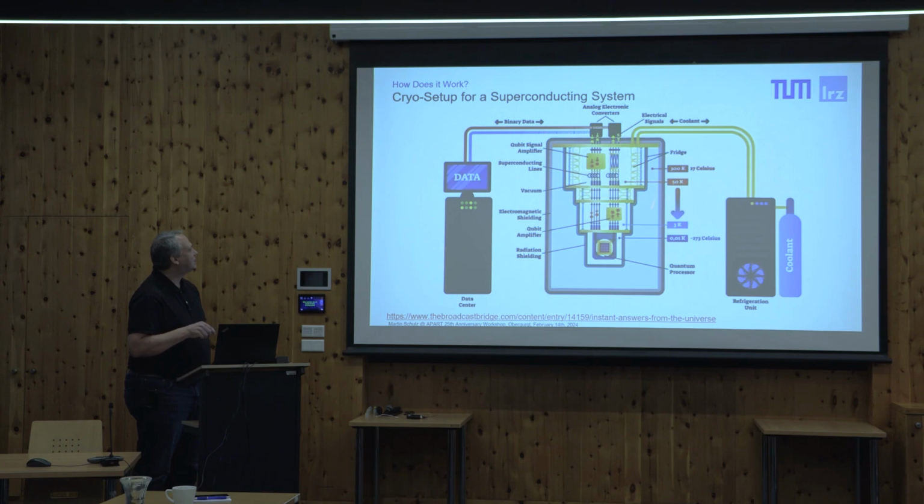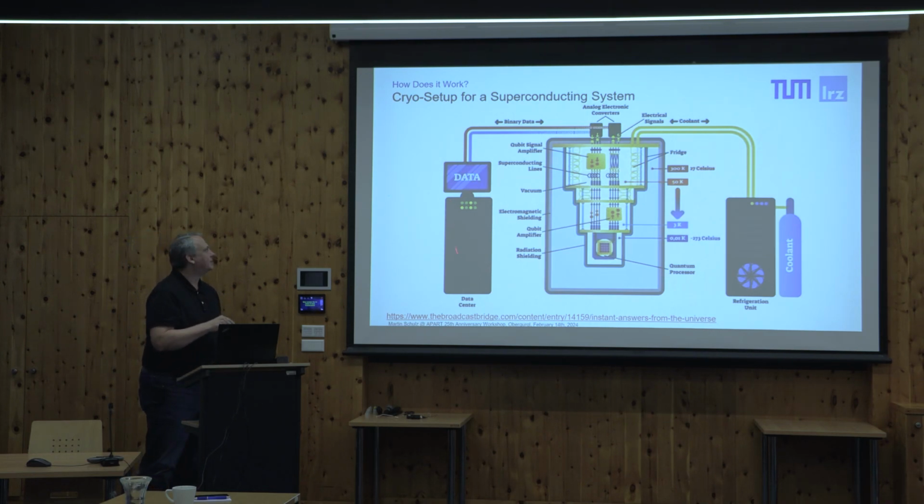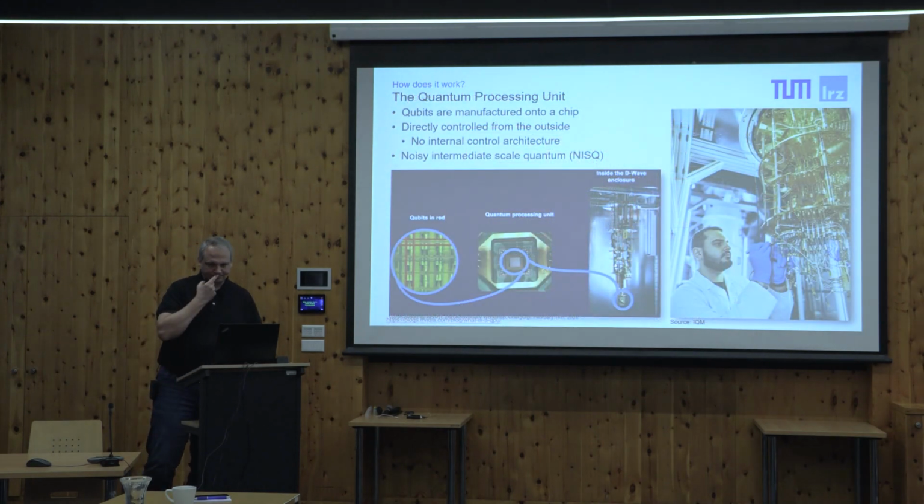And that's the beautiful chandelier we always see, right? This beautiful golden chandelier with all these loops in there. Loops are just cables to get the microwaves from here to here. That's all it is, right? There's nothing fancy in that except to get the engineering right. And then you run the microwave cables here, and there's a computer on that side where you have the microwave generator that then goes out to the system. And basically, this is what you program. This at the end here, you can't program anything. That just reacts and builds the quantum states.